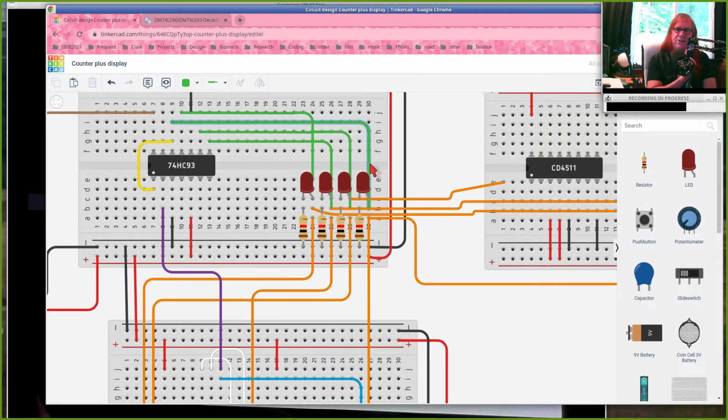So 1 wire per hole. Make sure all your parts are sitting on the board, right? In Tinkercad, I can actually have this chip just hanging off on the side here, and I can still connect to it, but make sure they're actually on the board. Don't run wires underneath chips, because you can't do that on a physical board. Run them around.